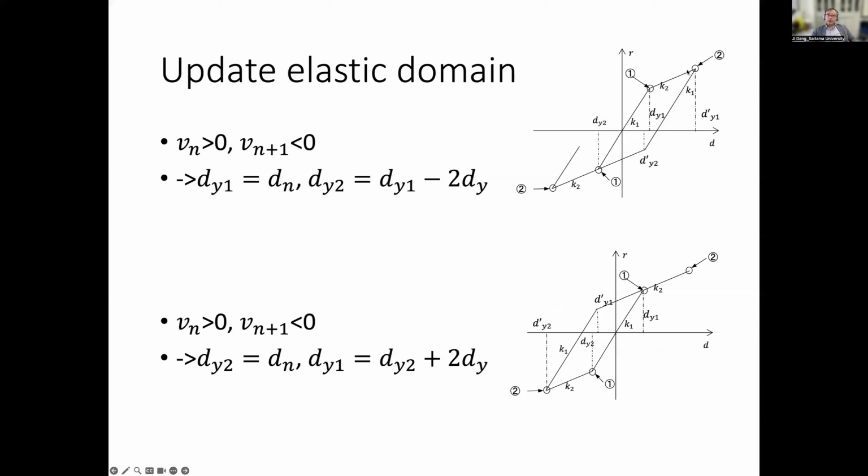So how much do we change? We use the unloading point, which is the most loaded point, as our new boundary of the elastic domain in the positive direction. For the other direction, I calculate it from the span of the elastic domain, which is 2 times dy.